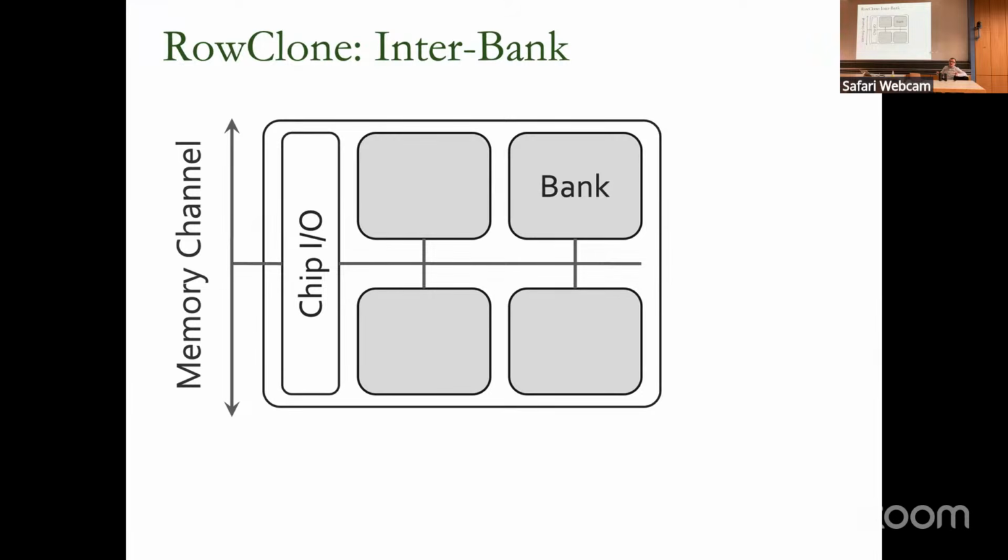And what if you want to copy things that are not at the page granularity? A page copy is a special primitive that's used in forking, for example, and when you initialize huge amounts of things like pages, multiple pages, many pages. But what if you want to copy one byte to another byte, right? That is also supported, although it cannot be supported in existing DRAM chips while violating the timing parameters. No one has discovered that yet. If you discover that, that'd be a big discovery, in my opinion. In my opinion, very tough.